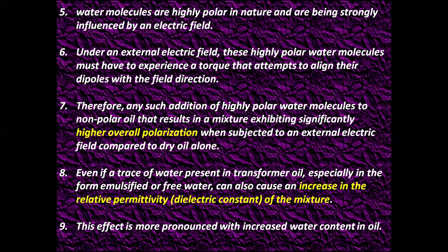Number 7, therefore, any such addition of highly polar water molecules in nonpolar oil results in a mixture exhibiting significantly higher overall polarization when subjected to an external electric field compared to dry oil alone.